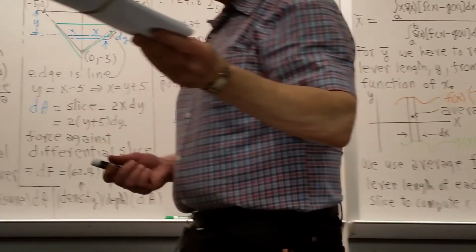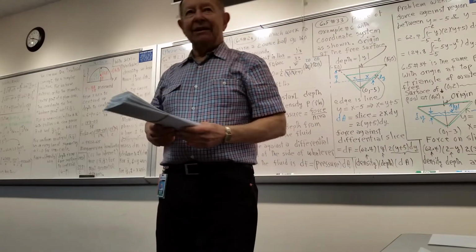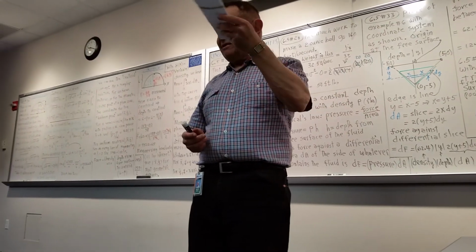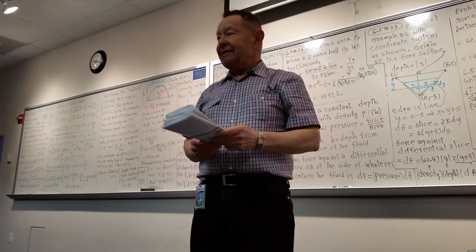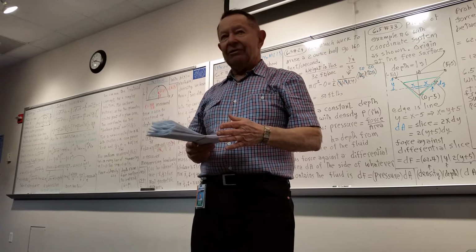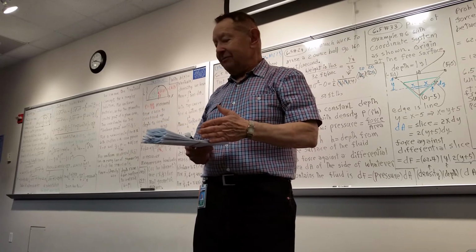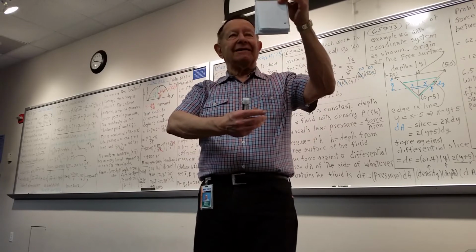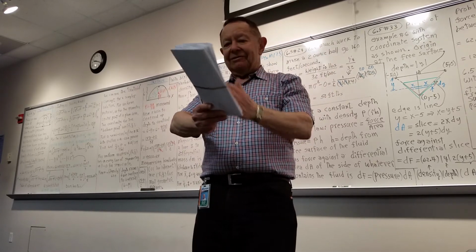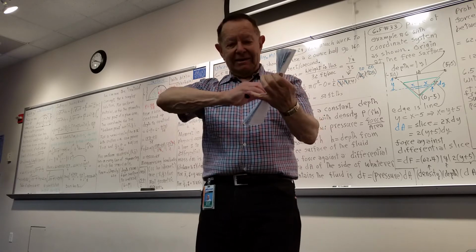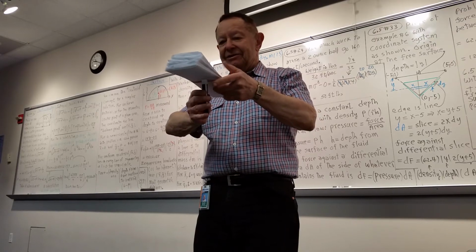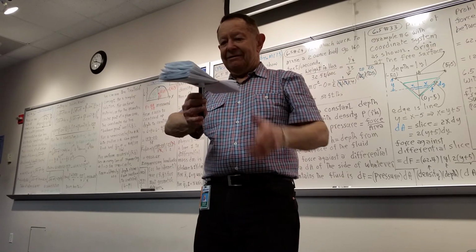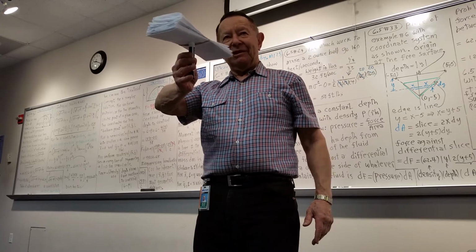Here's some homework papers. Paper is quite uniform. So if you have a geometric figure or a figure made of uniform material that's like a plane, then your balance point will be on every line of symmetry. So for a rectangle like this, you'd have a center line this way and one this way. And so approximately where the center lines would cross, you see you have your balance point.